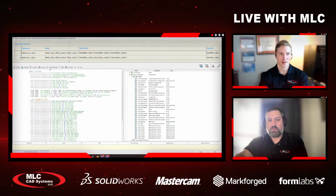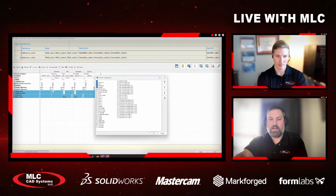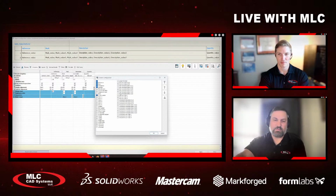Now, what I want to do is go to this columns tab and add something that's already been added to this query. So all I have to do is right click to the right of the last column, or you can hit the plus column button, which is add column. Either way will bring you to this. Now, because article number is a built-in piece of information, you can just check it on. Otherwise, you would have like a user data field or something like that.